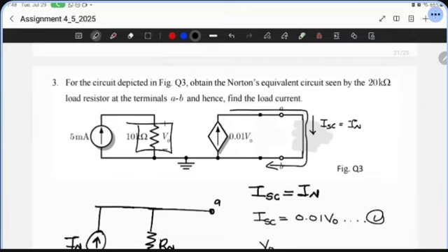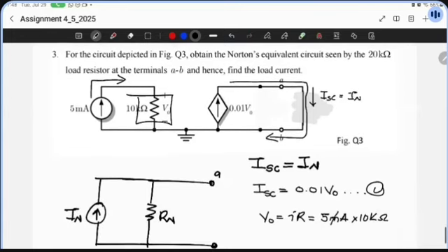Voltage is equal to current times resistance. The current passing is the same current being supplied here, so the current passing is 5 milliamps. The resistance receiving that current is the 10 kilo ohms. So the milli and the kilo will cancel each other. So we only have 5 times 10, giving us 50.